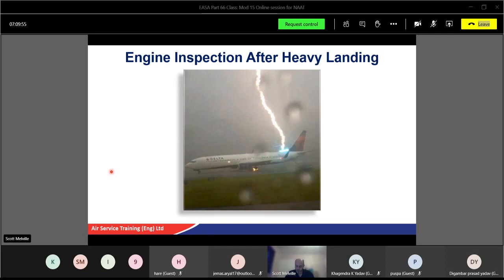All right. If you were looking at the back of the engine, you're looking at the LP turbine, you're checking for discoloration, and you found some deposits there, and they were sort of bright blue or golden speckle, what would that be indicating? What type of material? If it is golden blue, then titanium. Yeah, good. For aluminium? White and silver. White and silver, good. This is a nice easy section, yeah?